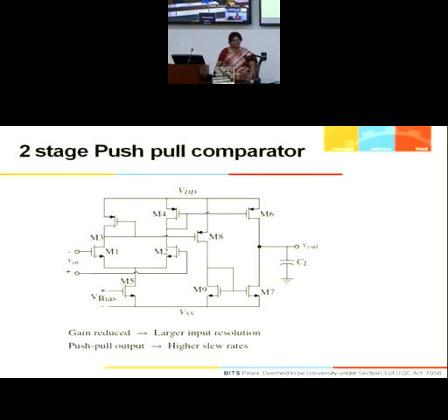So for the amplifiers we have seen till date, the input goes to only one transistor, and the other is a current source load, diode connected load, or resistive load, no? But here the input is going to both and it is working, similar to a CMOS gate. Let me draw it on the sheet of paper so that you understand.